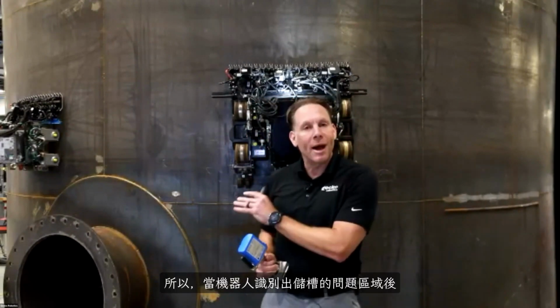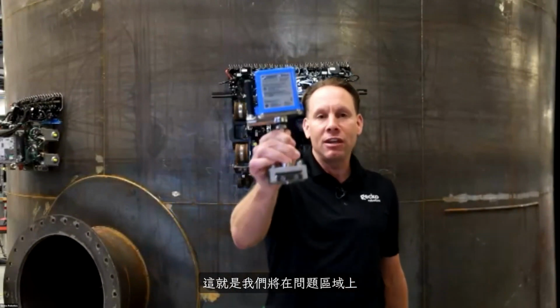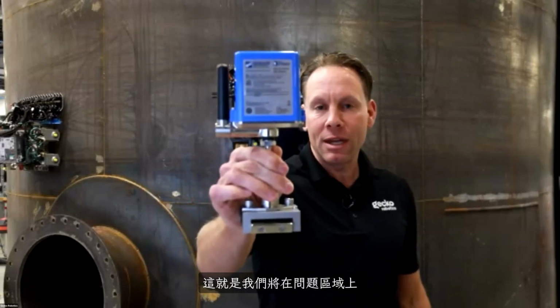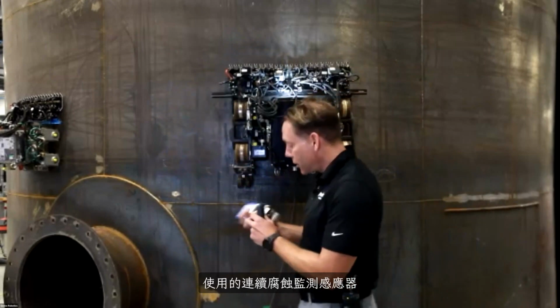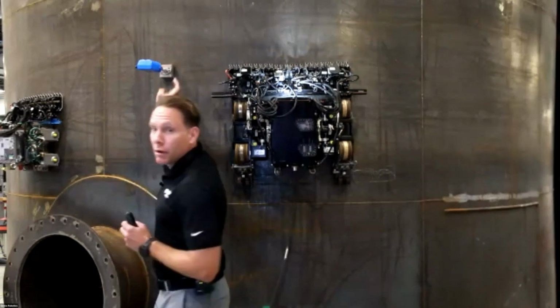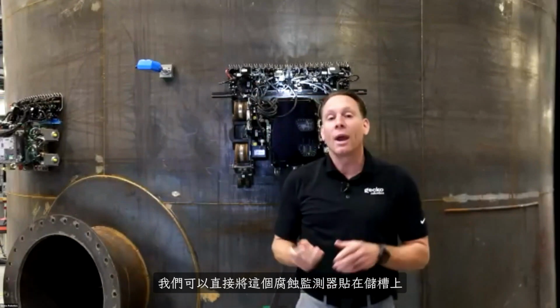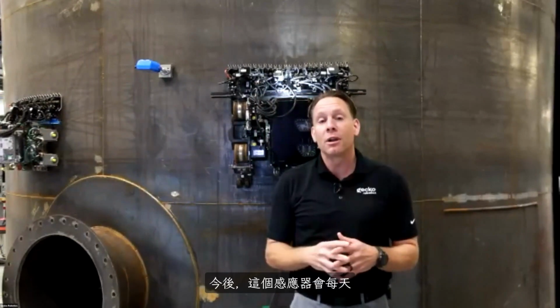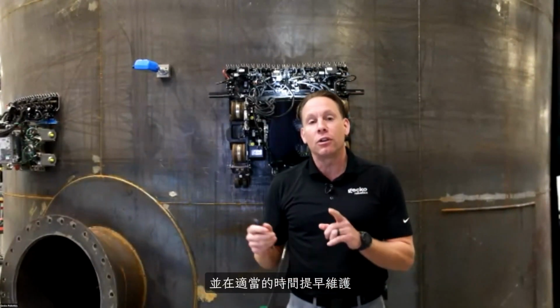So once the robot has identified the problem areas on your tank, this is the continuous corrosion monitoring sensor that we go over to the tank, and wherever the problem area might be, there's a very strong magnet, so we just stick that corrosion monitor right on the tank, and moving forward, that is what's going to tell us every day what the corrosion level is in that area and is going to trigger maintenance at exactly the right time.